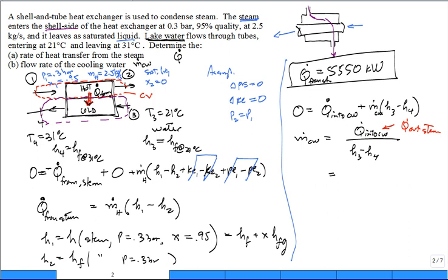Heat exchangers, by nature, don't transfer heat to the surroundings. They transfer heat within the boundary of that heat exchanger between the two fluid streams. Sometimes, if I haven't said it already, it sounds like an oxymoron. It's an adiabatic heat exchanger. What? Adiabatic meaning no heat transfer, but it's adiabatic with respect to the surroundings.